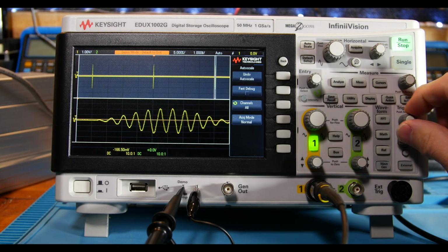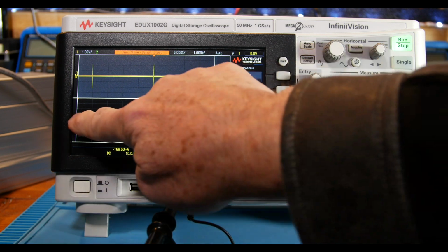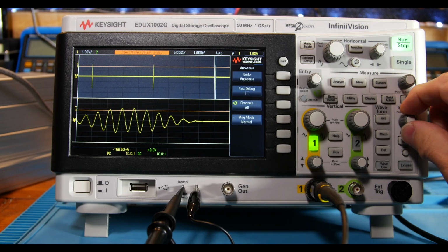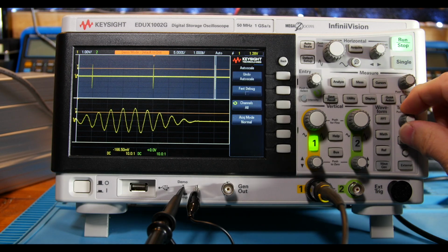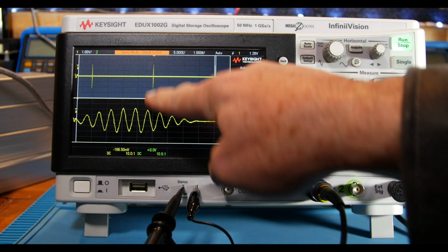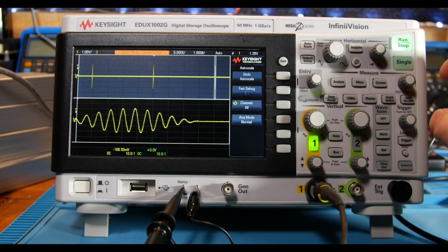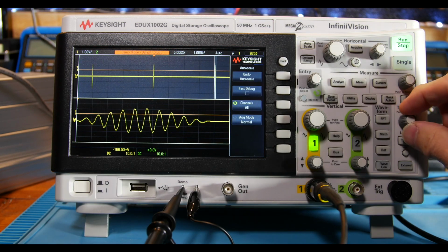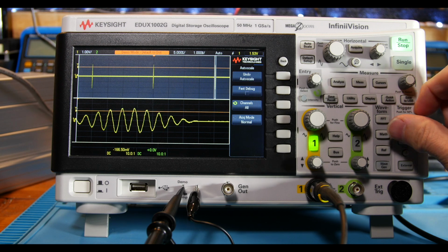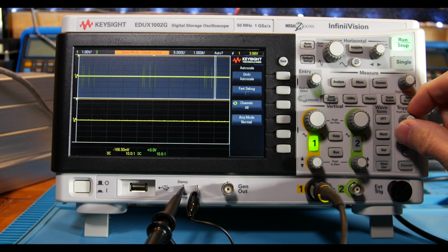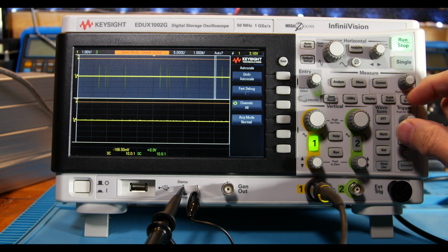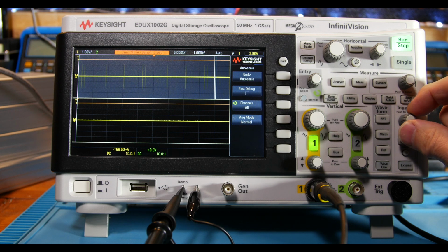Now, see where the trigger is? It's right here in the center. You can see the little T over here, maybe, hopefully. And up in this window, you can kind of see where I'm moving it based on this signal. So here, I'll move it around so you can watch it. See, when I go above the signal, then it's not capturing anything. So I have to bring it down, and I might want to be looking for the highest peak signal. If there is one, it'll trigger on it.